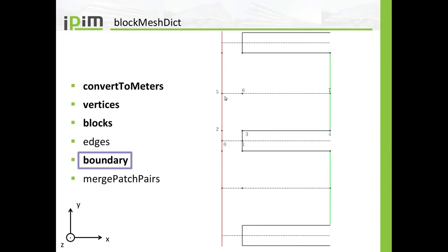What you end up with, here is your geometry that we define here with the inlet and the outlet, and you can mirror that to the top and to the bottom, and then you can continue on mirroring it further on, and what you end up with is a set of semi-infinite long plates with a certain gap in between them, with an inlet here and outlets here, and you investigate the two-dimensional flow in between them.